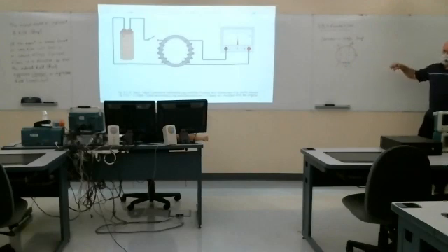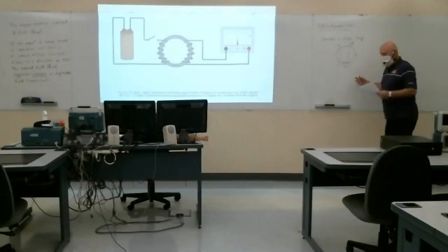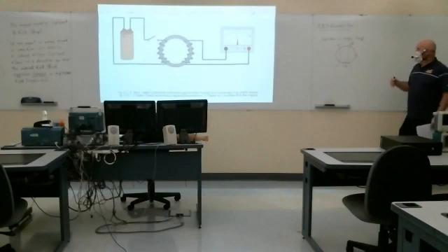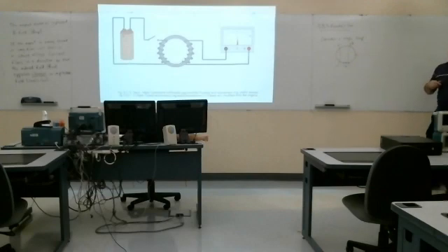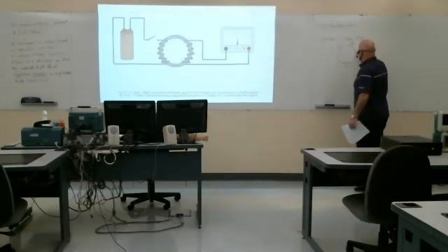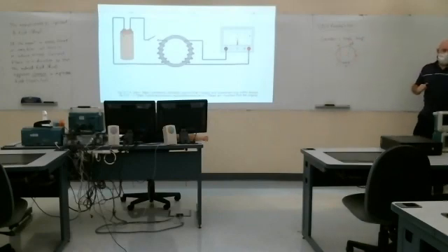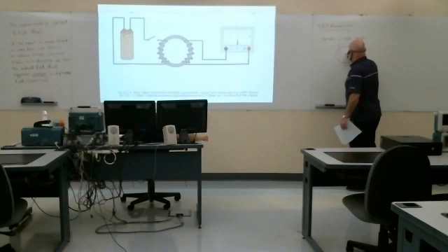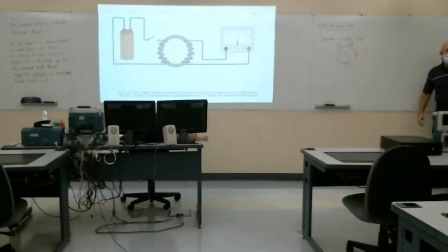And that's tied to the polarity of this voltage. The other thing that we'll see, we need to evaluate a surface integral here as part of Faraday's law. And so I need a normal to the surface enclosed by this loop. I say the loop is bounded by a contour, and my contour integration is in the same direction as my current. Now I apply a right-hand rule, which means my normal to my surface would be in that direction. So if you get this wrong, you're going to be off by a minus sign.